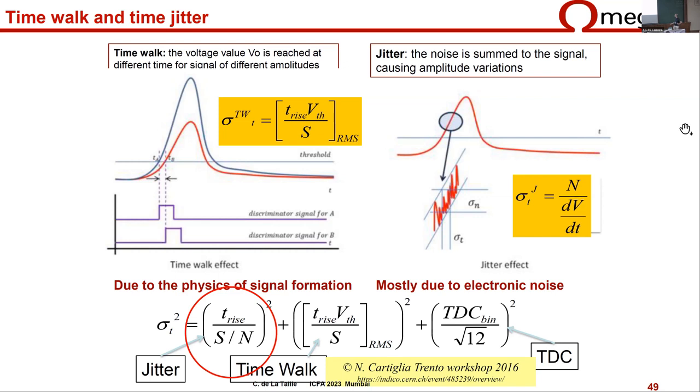and do the correction. The second effect that you encounter is the fact that, again, due to noise, you will pass your threshold when the noise is helping or hurting, earlier or later. You have all looked on an oscilloscope at the discriminator. I think there is a lab class also on that. So you look on your oscilloscope at your comparator output or discriminator output, and either you add noise or you put in a small signal, and then you see your discriminator output wobbling like that. We call that jitter. This is just due to the fact that there is noise on the waveform, and so when you cross the threshold, it will depend on the noise and, of course, once again on the slope of your signal.